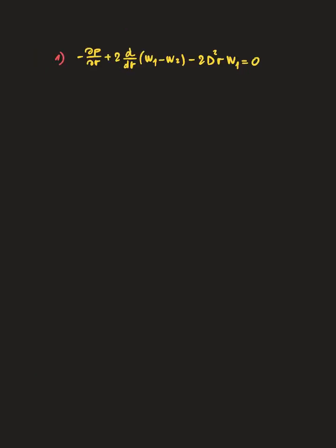So I've just copied the expression, the equilibrium equation in the radial direction. And remember that we're doing all this to compute the pressure. Once we know the pressure, we know all the stress components. And from this expression, as I told you before, this actually can be rewritten as P prime of R, because it's just a simple derivative relative to R.